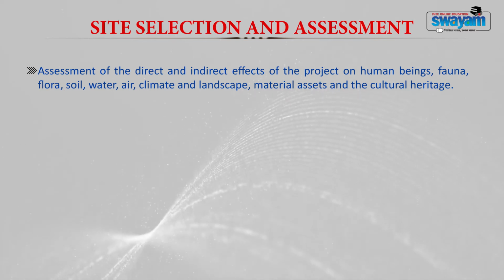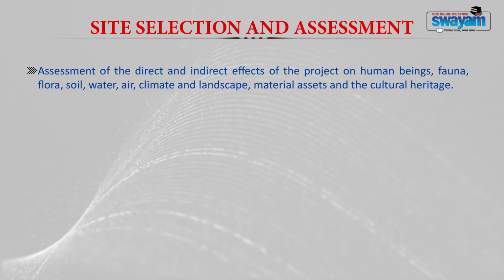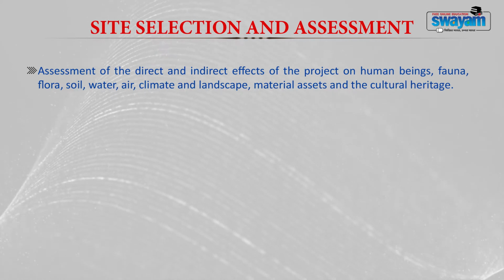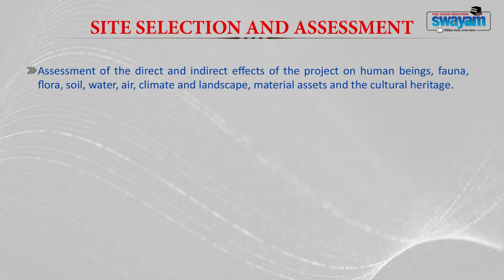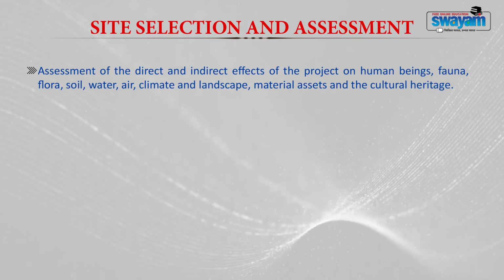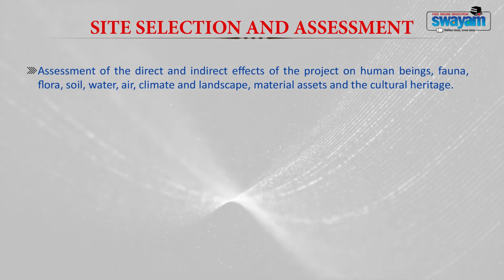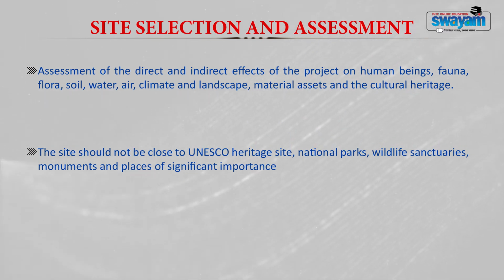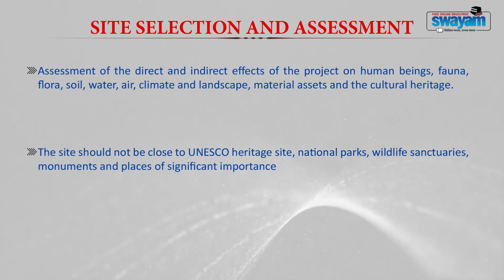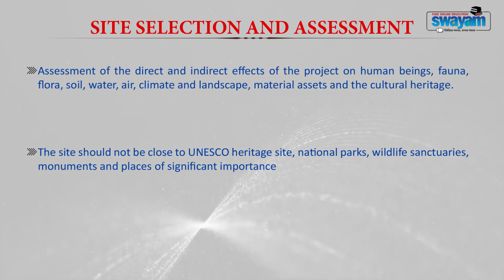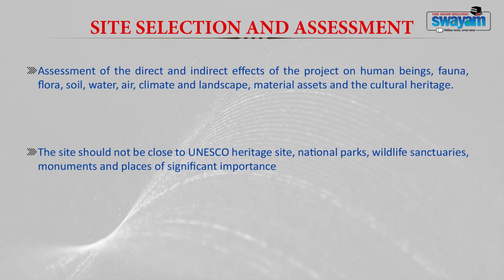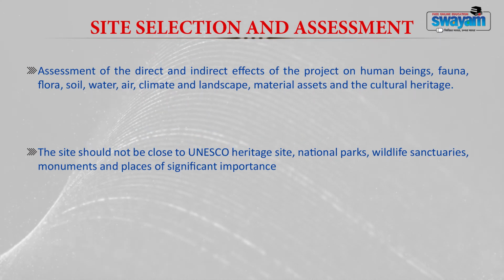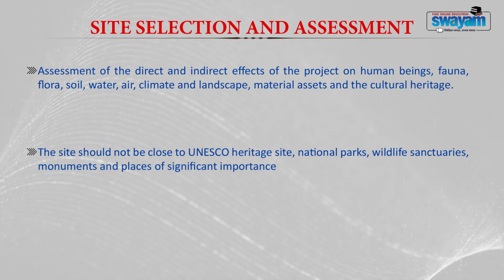Also you should take care if there is any cultural heritage area around; you should see what impact this particular site is going to create on these environmental components as well as the ecosystem. The site that you select should always be away from UNESCO heritage sites, national parks, wildlife sanctuaries, monuments and places of significant importance. That means the site which you are selecting for landfill should be away from all these areas. It should not be near wildlife sanctuaries or wildlife corridors, monuments and any UNESCO heritage sites.